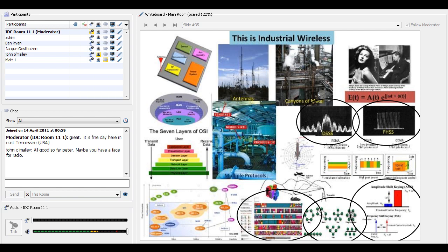On the left-hand side, this is what every field device looks like. Every field instrument, I don't care who the vendor is, looks like that. It's got a sensor, it's got an intelligent controller, a microcontroller inside it, it's got a power system, it's got some circuitry. Auxiliary circuitry would be like this little ASIC that's sitting right here doing something. If it's wireless, it's going to have an antenna and a radio. If it's wired, it's going to have just a cable coming out of it. But the rest of the stuff is all the same, and you'll see it. That's the common design, the generic design for all instrumentation.